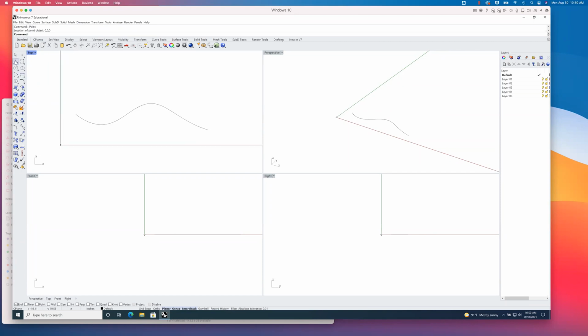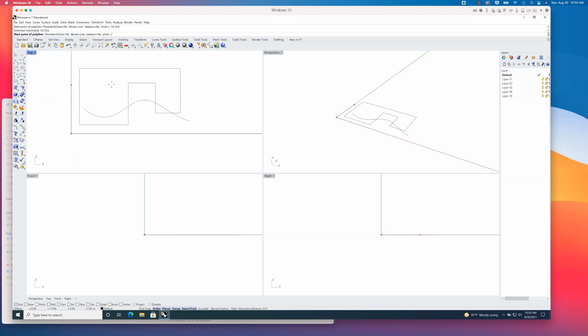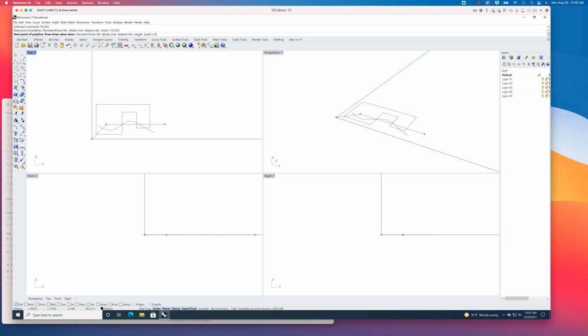Okay. Again, I can go around and start a polyline. I can click, and I can turn on my ortho even, and start to make 90-degree angles and start to draw, let's say, some sort of walls. Try to make things align, close them up. Or I can literally start to type in explicit coordinates for each of these points. So the next point out here, the next point out there, and on and on and on.